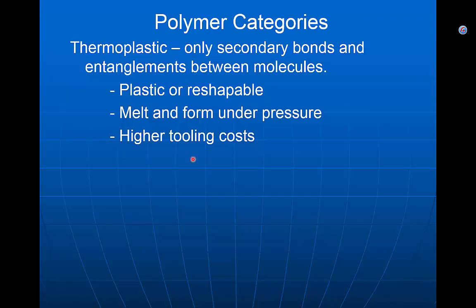The issue with thermoplastics, they are not that expensive necessarily, the resins, and there's many of them that are very cheap, but they generally require fairly high pressures to get precision parts in the reforming process, and so we're often talking about fairly expensive tooling for making these materials. But the ability to heat them up and reform them means that scrap can be ground up and remelted and reused, turned into final product, so they can have very low waste levels when we work with thermoplastic.